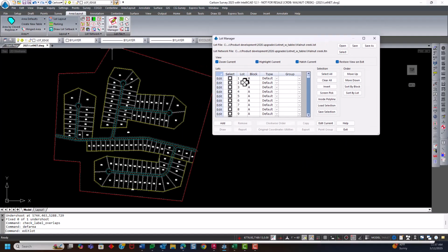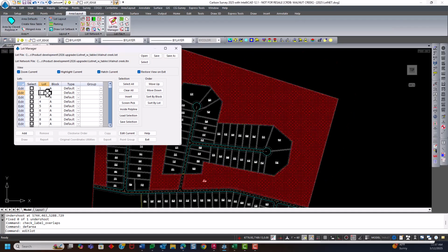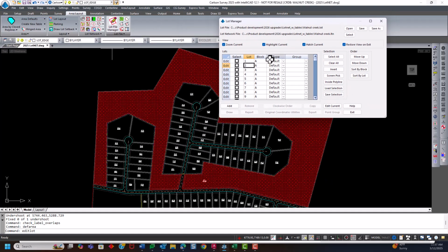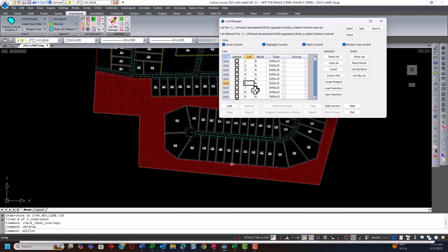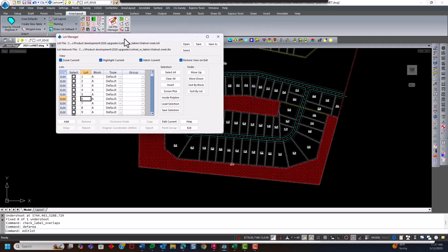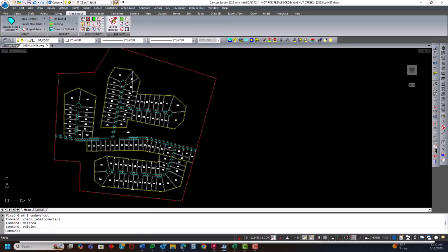And you can see we have lots created out here. I can click in them. That's the open space parcel is 2, and then we've got 3, 4. They're kind of all over the place. But the thing to notice is that they are all in block A currently. So there's 111 lots all in block A. So we're going to change that.